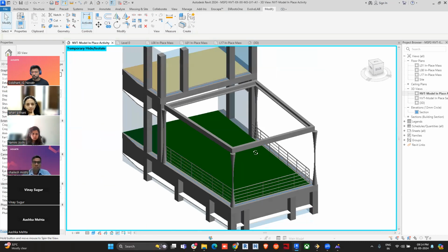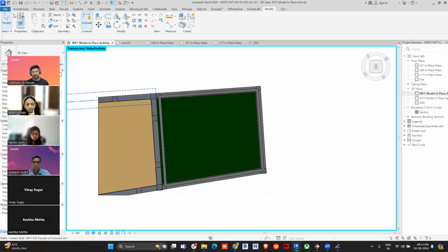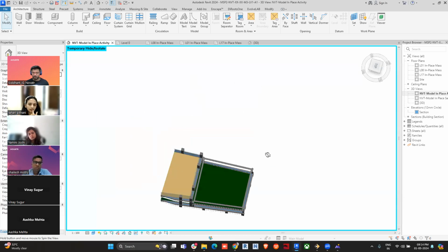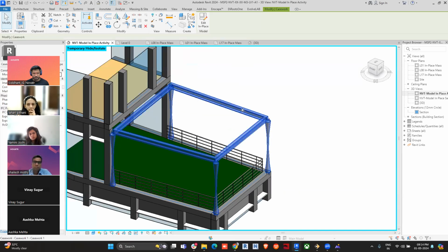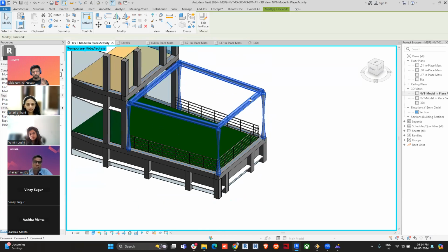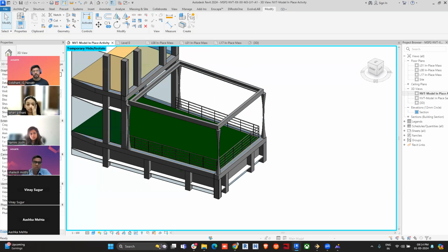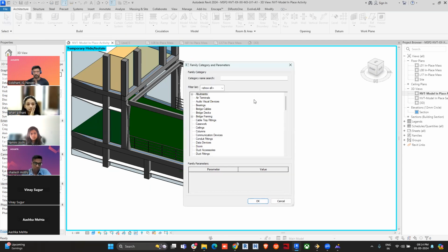And now we will go to top plane, and we'll create the slats. For that, I will go to the architecture tab again. As you have noticed, I did not finish the tool when I was working on this particular frame. So I prepared both of them inside a single element. That's why whenever I select it, it comes out as a single element. If I double click on it, then I get into edit mode, and then I can select them individually. If I finish this and create this thing again, that will be one separate entity. So these are all different elements.